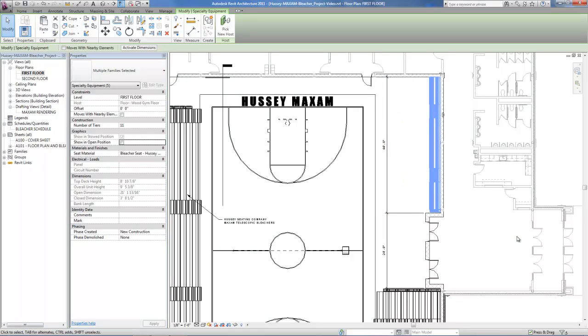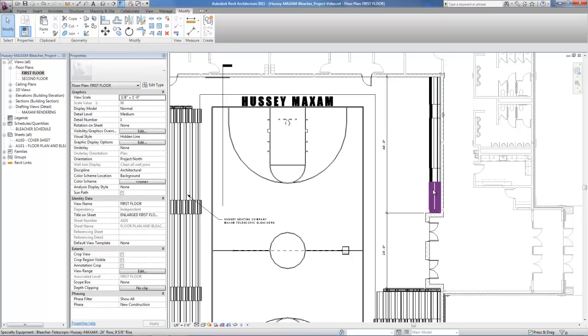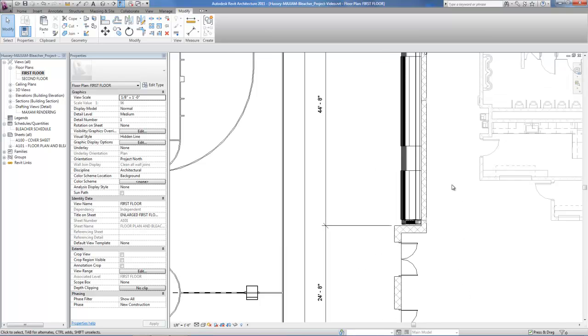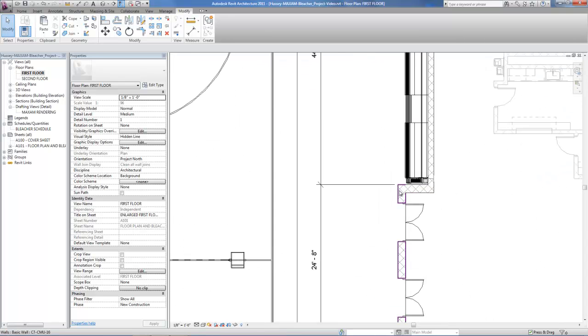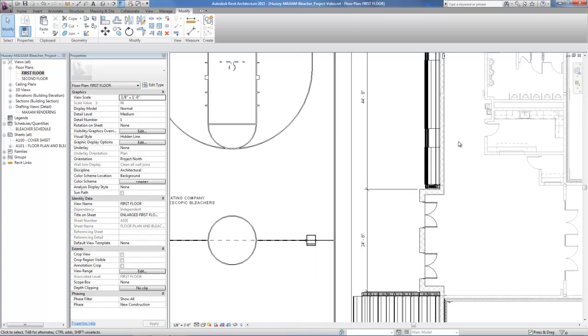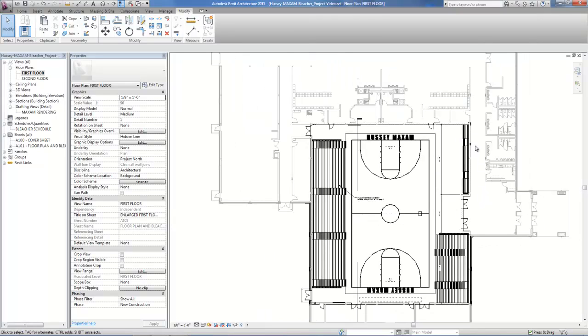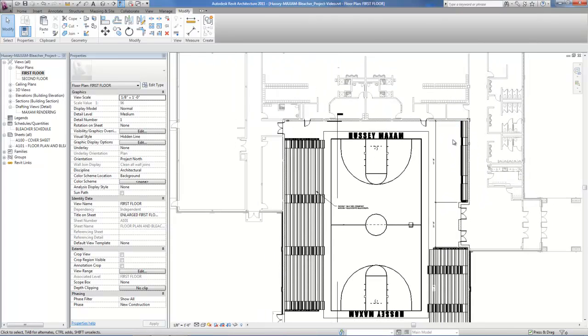The dimensions have been coordinated with the specifications, so no matter what your row spacing is, whether it's 22, 23, 24 inch spacing or 26 inch spacing, the open and closed dimensions will always be true to the specifications. The architect can now verify based on that he has a clean corner here and he's in good shape. He doesn't need to relocate this wall to satisfy that. And as you can see, that is an instance-based property, which means that all of these ones can be closed and all these ones can be open, even though they're the same components.